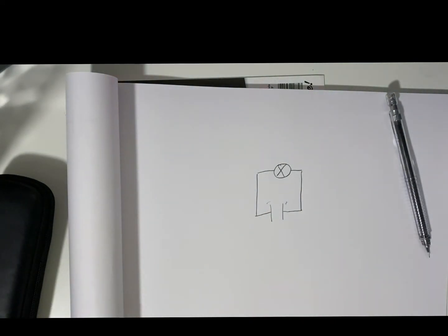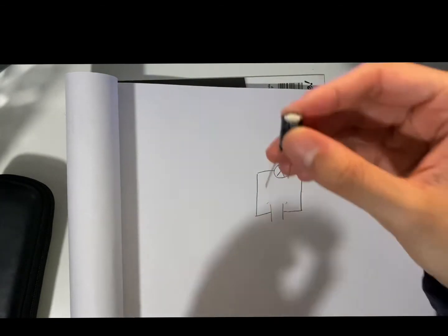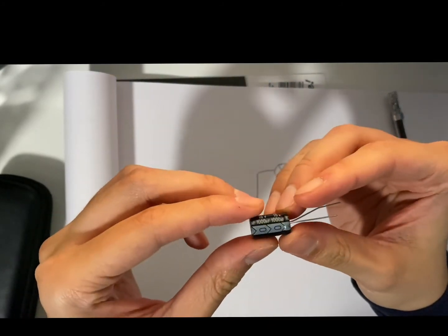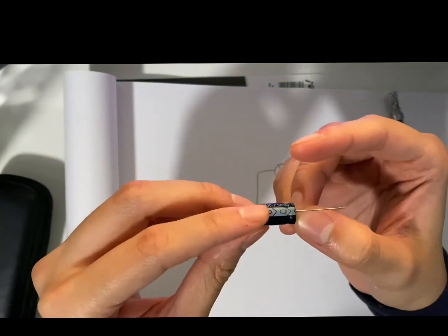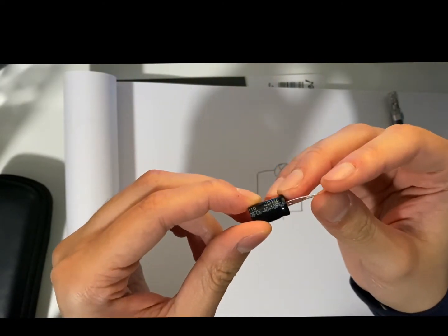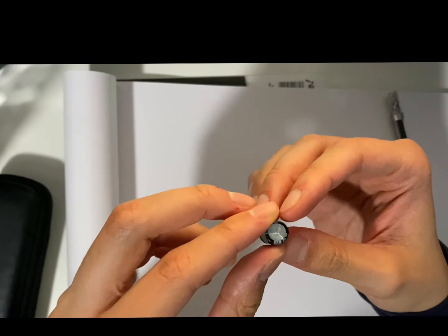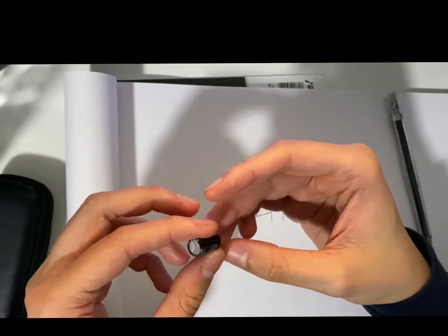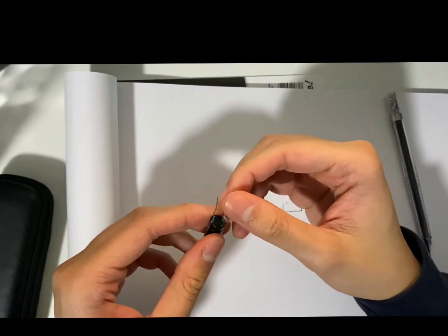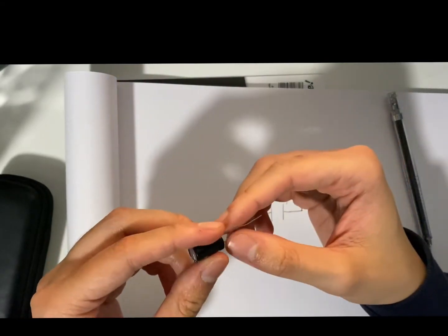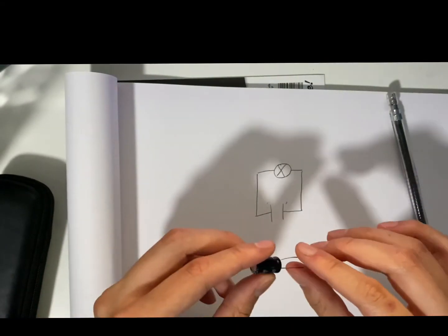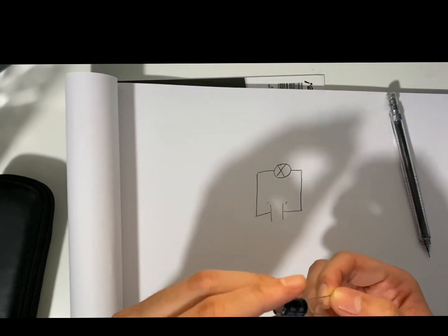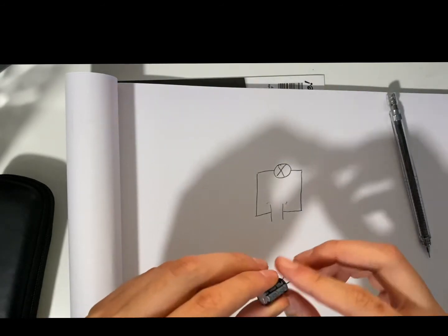So just going to get my capacitors here. This is how a capacitor looks. You can see we have a negative terminal here, and we have a positive one. This type of capacitor is called electrolytic. We can get many different ones: ceramic based, film ones. So this one's electrolytic, and these are sensitive to their polarity, hence they have a rated voltage, and as well they have a negative and positive terminal.